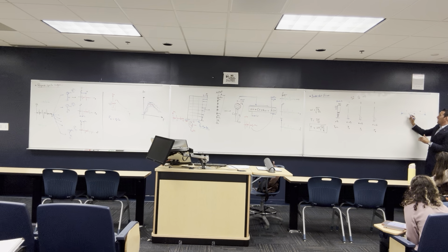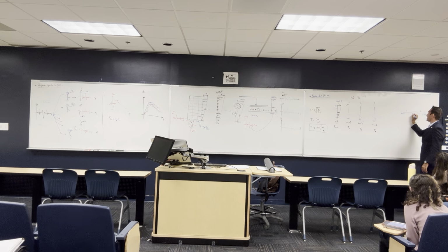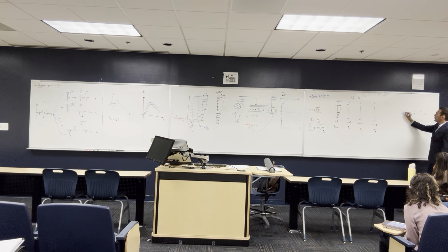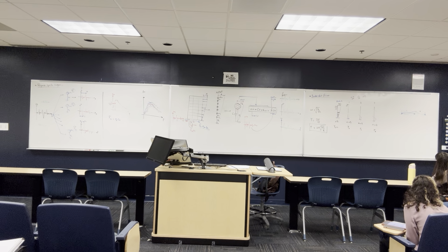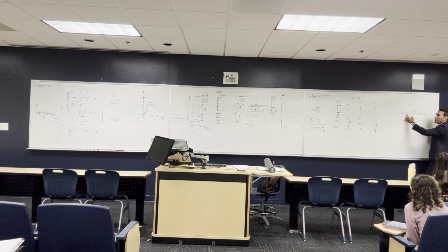So the thing is, we put the reinforcement where the tension is. When we do reinforced concrete, we don't put it randomly. If there is tension, you will find most of the reinforcement here, and here there's minimal reinforcement. So maybe here you will find 10 bars, but here you will find only 2 bars. Here the tension is up, so you'll find most of the reinforcement here, because here is compression. Concrete can take care of it. But if there's tension, concrete cannot do anything. If you didn't put reinforcement, the section is gonna crack. So the same thing here. I put reinforcement here. And by the way, look at this. The maximum bending moment is here. So we'll find that all the reinforcement lengths are not the same.